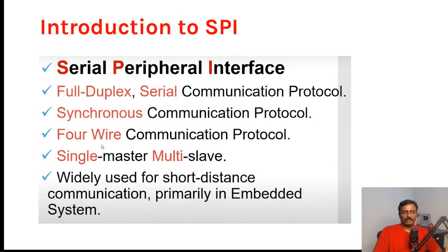UART is widely used to connect with GPS modules, and wherever you need to send data over a long distance, like 3 meters, you could use UART. But it's widely used for connecting two devices at a time. When you try to connect more than two devices on a single UART, that leads to bus contentions.